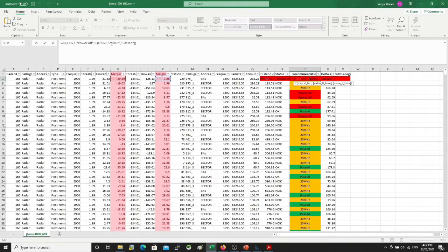So you can recommend 20 megahertz or 40 megahertz or 50 megahertz reduction to your transmission bandwidth. And this is something case by case. Obviously, I cannot give you a generic figure now; depending on your network, how much overlap you have in the in-band, then you can propose a suitable shutdown or reduction of transmission bandwidth. Otherwise, it passed. Okay. So let me talk about each one of these first.